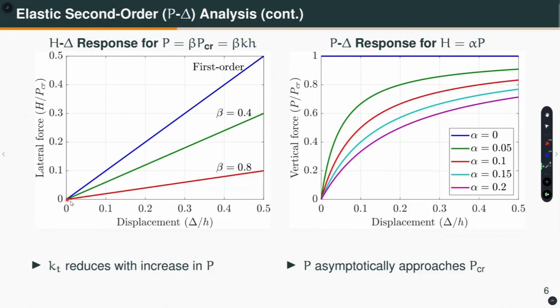So, then it is going to be like this. Then it is in critical condition, or it has reached the bifurcation point. So, the takeaway from this is that the gravity load cannot be ignored and we must consider the P delta effect. As you can see, the stiffness is significantly reduced depending on the amount of gravity load that is applied on the structure.